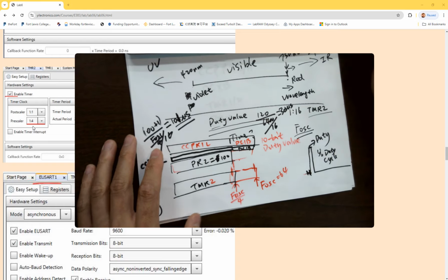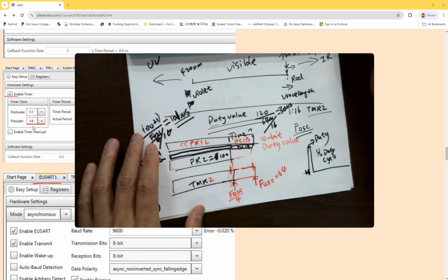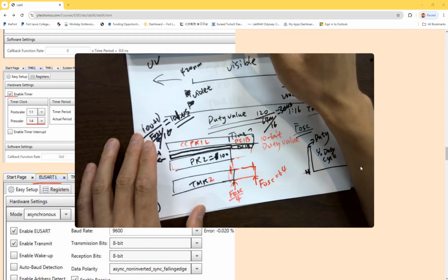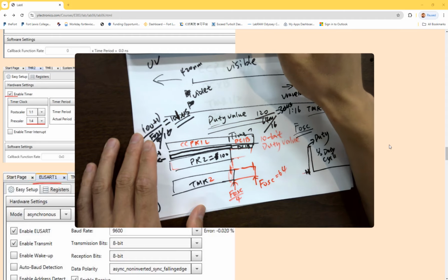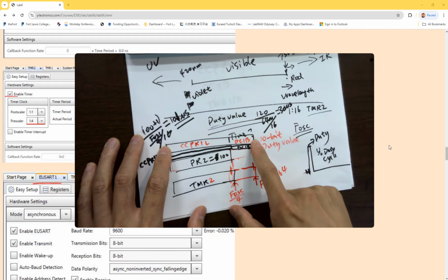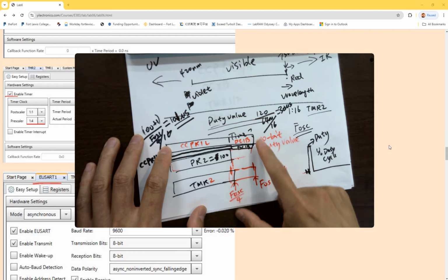What's that? For the answers, it's just 0.39 seconds. So it's a 1-to-4 prescaler. Oh, sorry. So how do you do that? 1-to-4 prescaler. I'm sorry. So 25 is the counts, right? Given the counts, calculate the time.